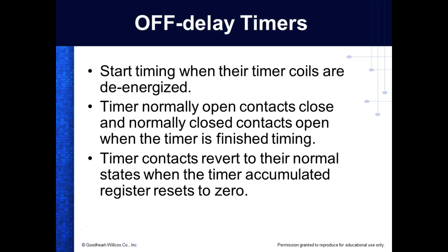Yes, they just have to be in parallel. You can't put two of them in series. One timer per line. We can have multiple timers in the same rung, right? Y'all understand that? So it's an output instruction. On an off delay timer, when you energize or make the rung true, all the contacts change instantly.